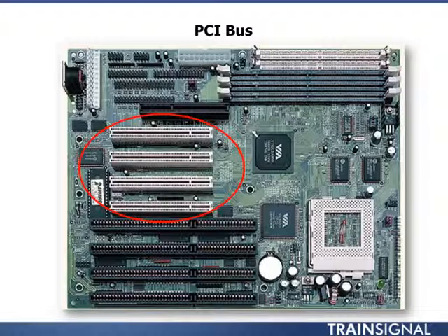The original PCI standard, whether it's 1 or 2.0, supported cards running at 3.3 or 5 volts, depending on the keying of the slot, and the keying is that little white connector piece that you see coming across. It's supposed to prevent you from putting in a card that's not compatible. And it would be either 64 or 32-bit.